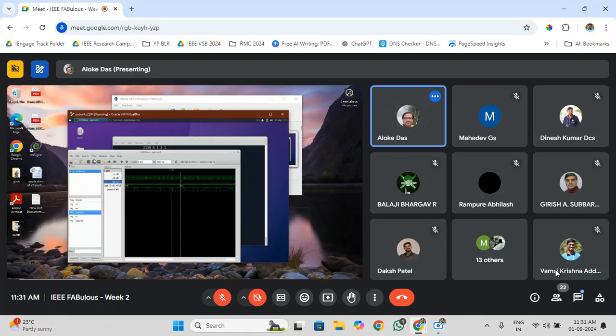So if I bring it into the same frame, see, initially it started with a 1 out of 8 duty cycle. Next I changed it to 2 out of 8. Then here it is 3 out of 8. So that is the PWM circuit. It changes the duty cycle, not the frequency. The frequency is the same from here to here. The time period is the same, but uptime and downtime are changed.